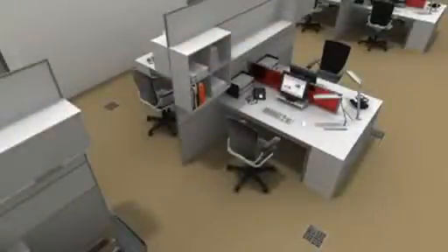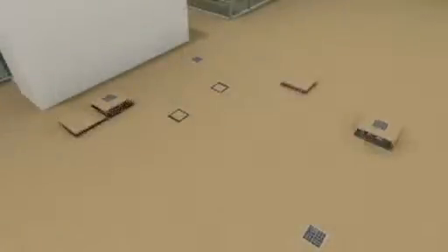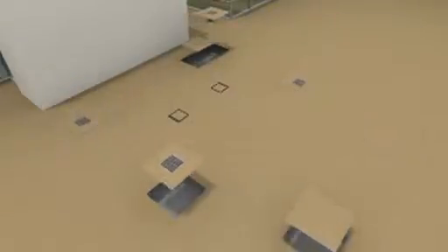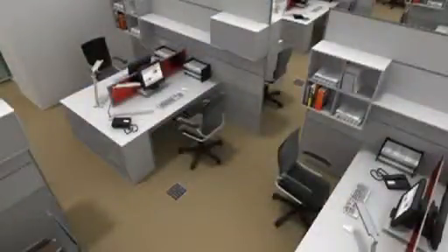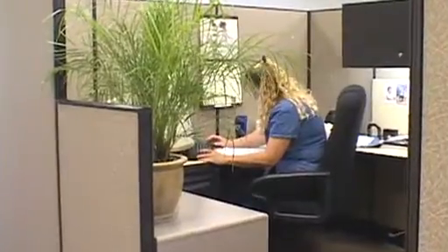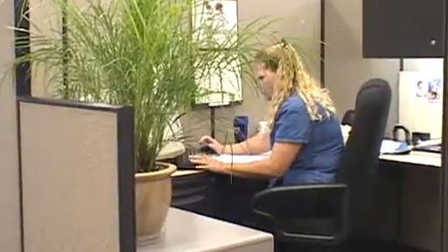If by chance a diffuser is situated under a desk or some other undesirable position, it's simple to pull up a diffuser tile and exchange it with a full tile from a location more convenient for the diffuser. This is a major benefit in commercial buildings when tenant reconfiguration is required.